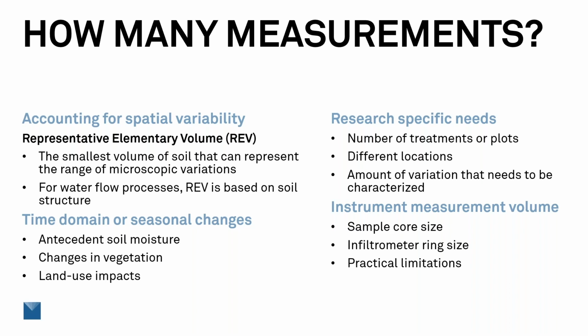In the field, say we're using a ring infiltrometer, the ring size of the infiltrometer that you're working with, and what are the practical limitations of that? You can only have so big of a ring in the field, and the bigger you go with your ring when you're trying to do these measurements, that typically means you're going to use a lot more water to make these measurements.